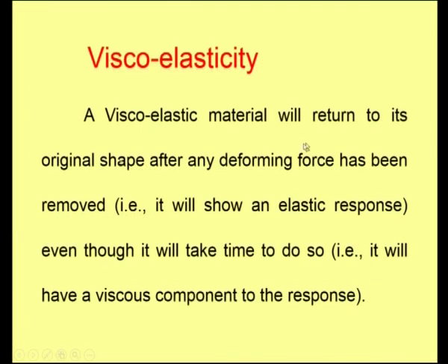A viscoelastic material will return to its original shape after any deforming force has been removed. Similar to an elastic material, when an elastic material is stretched and then left, when the applied stress is removed, it will come back to its original position, which is an elastic response. Whereas a viscoelastic material will come back to its original position, of course with a time delay, it will take some time to do that. This is called the viscous component of the response, which is viscoelastic.